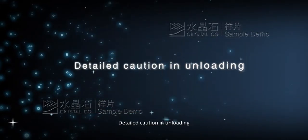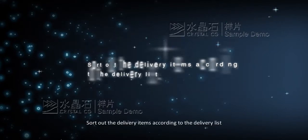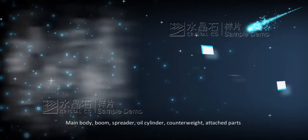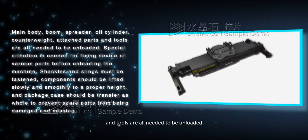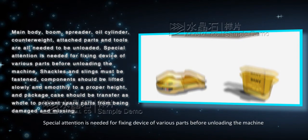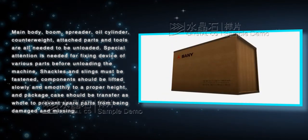Detailed caution in unloading. Sort out the delivery items according to the delivery list. Main body, boom, spreader, oil cylinder, counterweight, attached parts and tools are all needed to be unloaded. Special attention is needed for fixing device of various parts before unloading the machine.